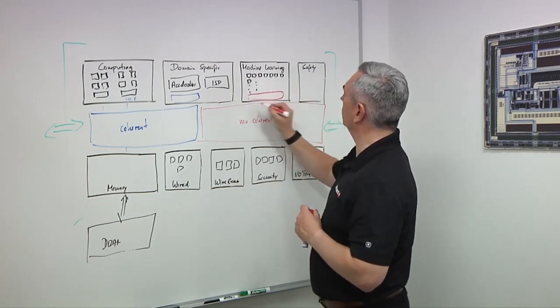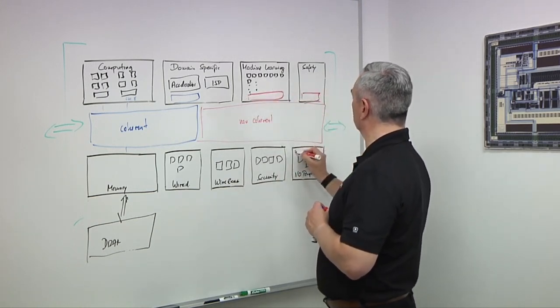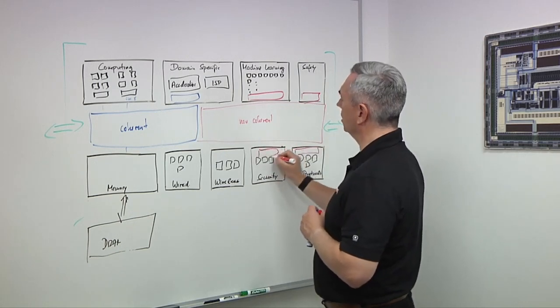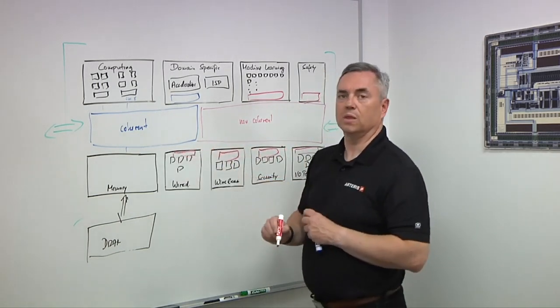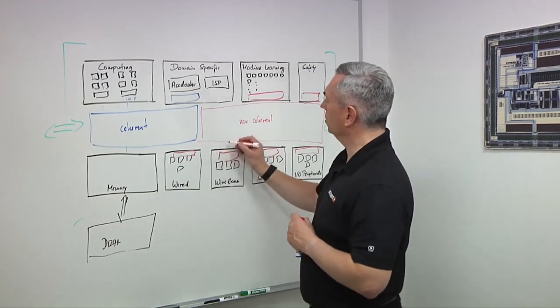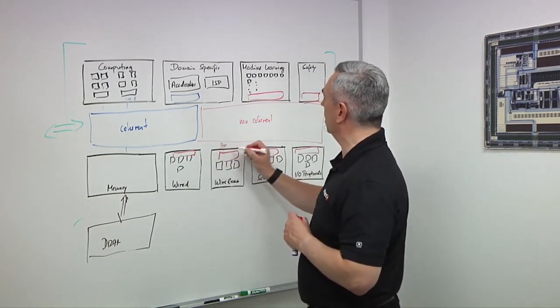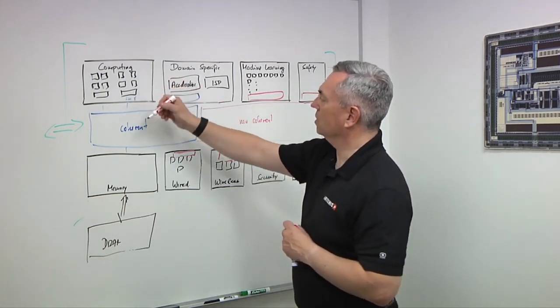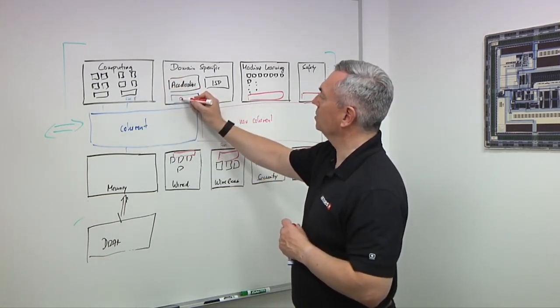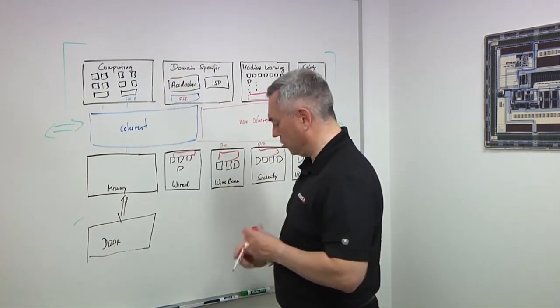So typically you actually find in these subsystems your own sub-networks, non-coherent. So those are the non-coherent networks in here. And here you speak things like AXI, you speak things like OCP. There's also then another coherent protocol here, ACE going on. That should have been blue.